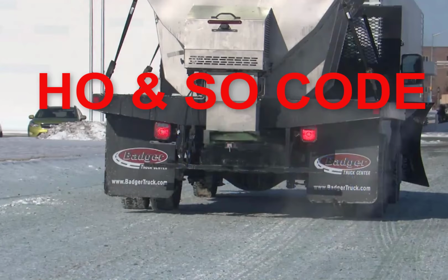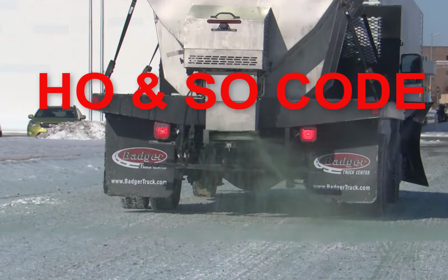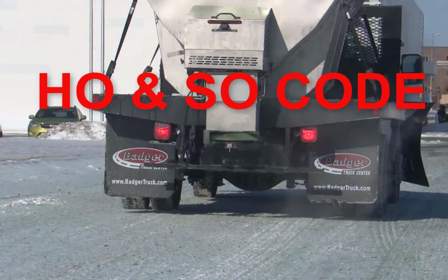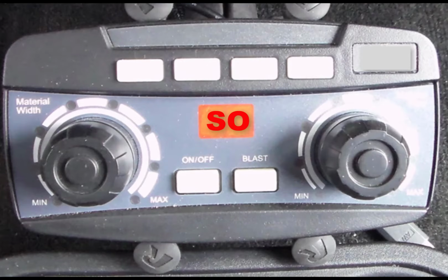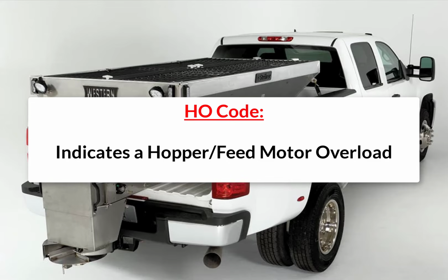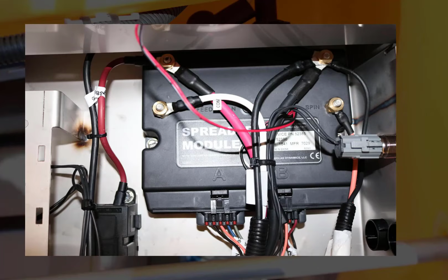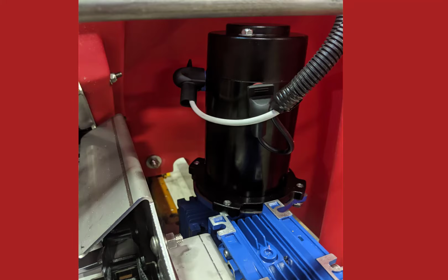The HO and SO code will cause your spreader to turn on briefly for a few seconds and then shut off, immediately flashing a HO or SO code. The HO code indicates a hopper feed motor overload, and the SO code indicates a spinner motor overload. If your control is flashing a HO code, the module is sensing that the conveyor motor is drawing high amperage. If the spreader is indicating that the motor is drawing too much amperage, the motors will stop running.